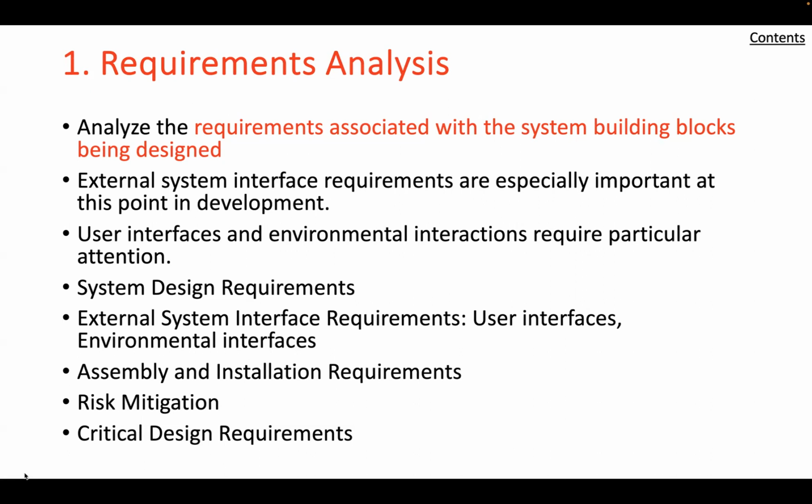The investigation of the accident revealed that a design change had been made at the assembly site because the originally specified long threaded supporting rods were difficult to install. A so-called "trivial" design change was made to permit easier assembly, but it increased the load on the rod structure by a factor of 2. The fault was attributed to those involved in the design change. However, it can be argued that if the original designers had given more attention to the difficulty of the assembly process, the problem and the resulting accident might not have occurred.